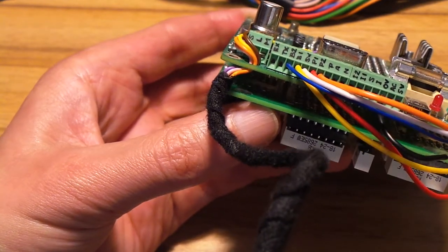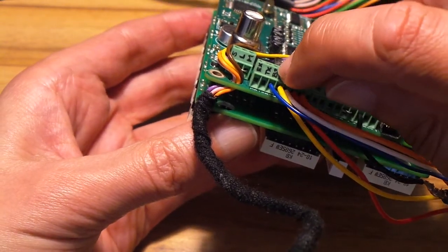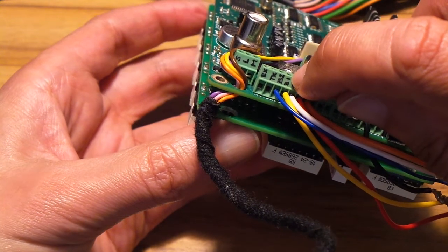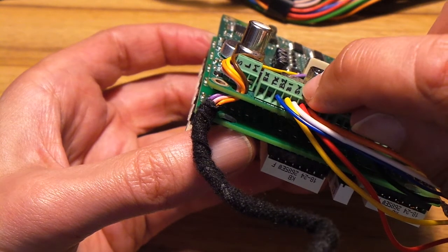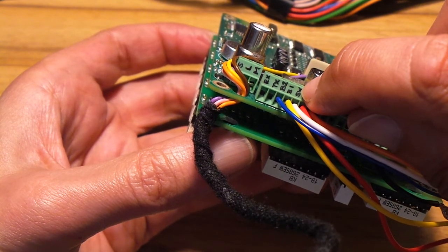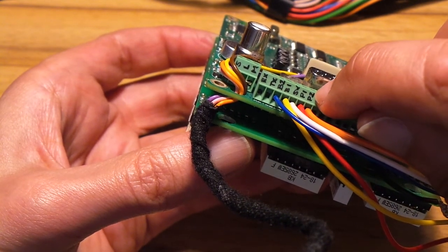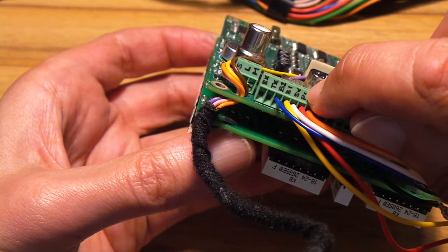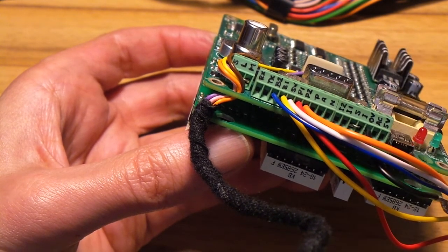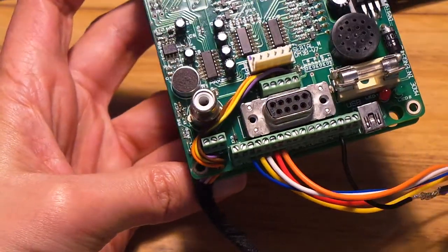These push buttons that we mentioned from this small box, which are ground switch discrete inputs, they go in on pins B1 and B2, so that's push button 1 and push button 2. The latching switch, which is also a ground connected switch, goes on the pin SW for switch. Potentiometers, which are variable resistors to ground, go in on pins P1 and P2. Normal auto pursuit would go in on here, but as we say, we've got them hooked up on this connector.